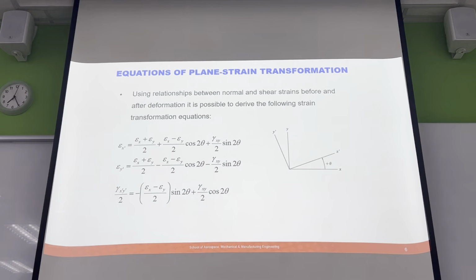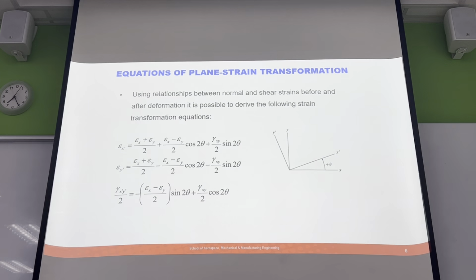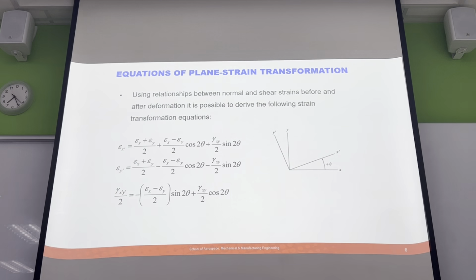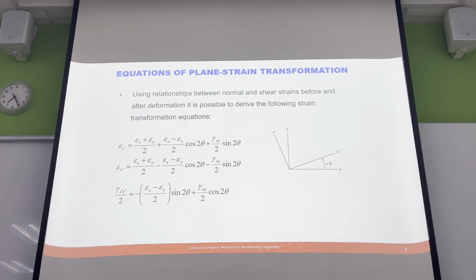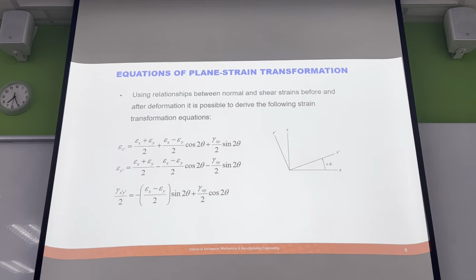They're basically little bits of resistive wire that when you pull them, they get more resistance. And so you can pass a voltage across it, and because the resistance is changing, there will be a voltage drop across it. You can measure the voltage drop and calibrate, and say, okay, if I put this much strain in it, this is what the voltage is going to be. If I put zero strain in it, this is what the voltage is going to be.